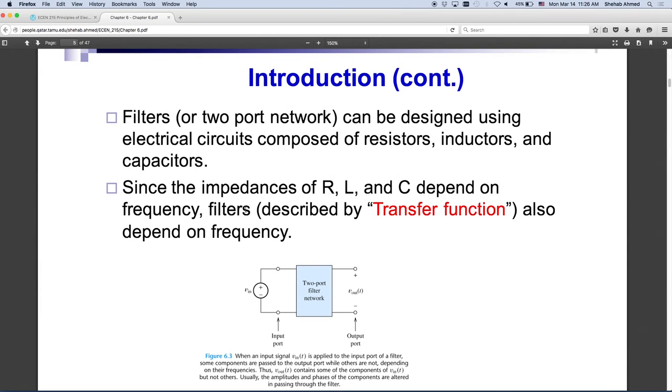And we cannot have a circuit that is pure resistors and talk about transfer function, can we? Resistors don't have any time dependence. The voltage and current signals across and through resistors have no relationship with time. You put V, you'll get I, exactly the same shape, scaled by a certain value of the resistor. But you put L's and C's in the circuit, and then things change with time, right?